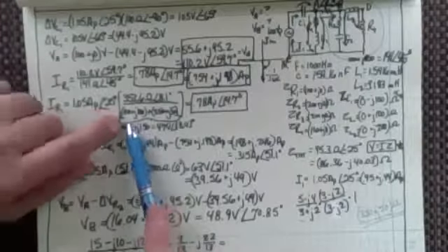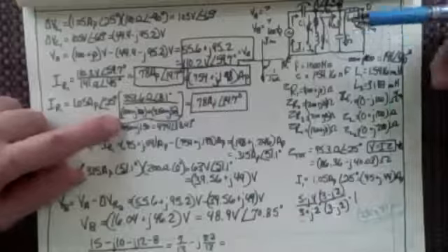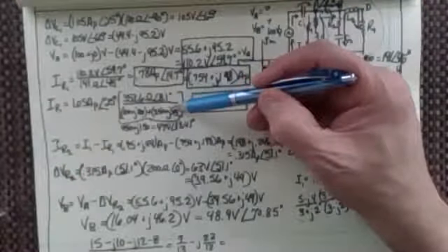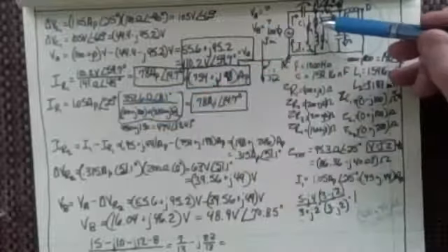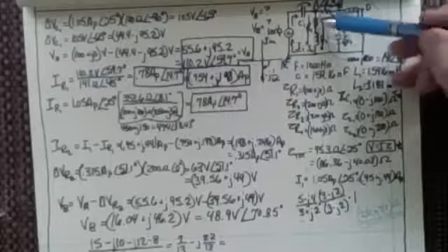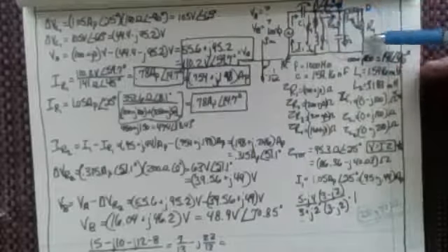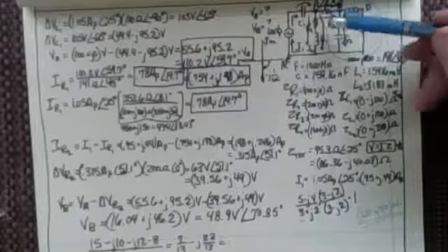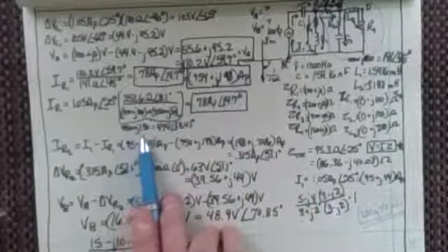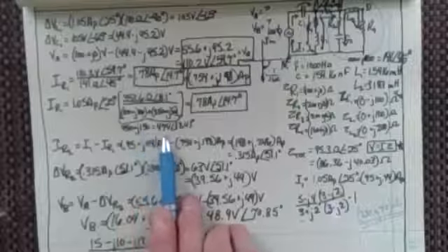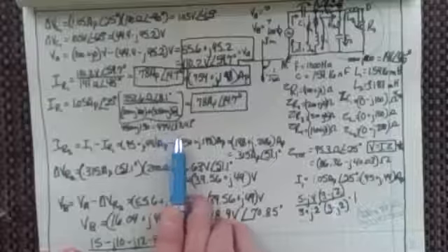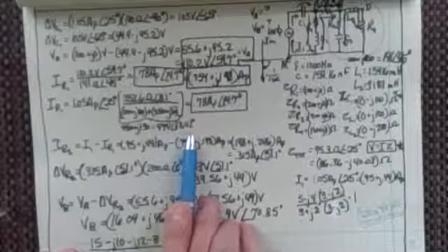And then on bottom, what I did was I added both of these together. So 350 plus J50 added to the 100 plus J100, which is here, right? So we add up what's in both of the two parallel circuits that we've got here on the bottom, and that's what I get, 450 plus J150, and that comes out as a phasor of 474 ohms at 18.43 degrees.